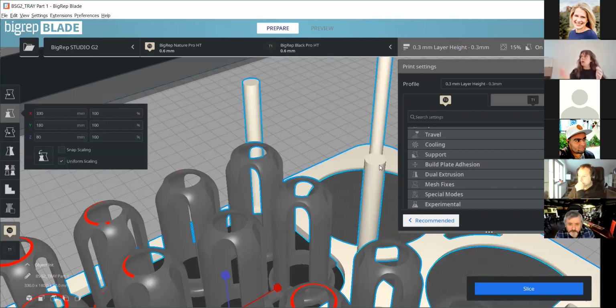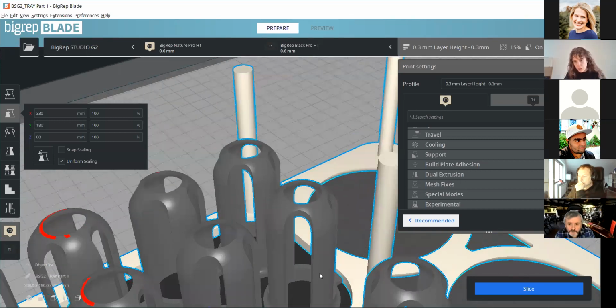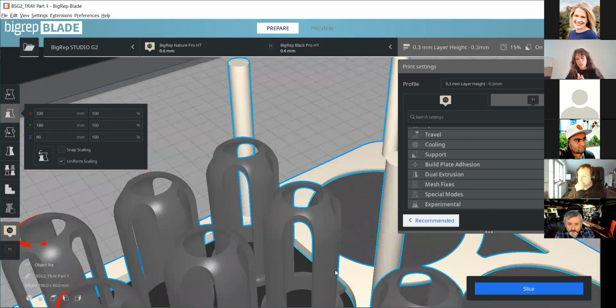But I modeled them so that the two elements, like you see this element here where they touch each other. Yeah. Those two meshes essentially are almost overlapping or right up against each other. So that when I bring it in here, when it prints, the outer layer of this element will adhere to the outer layer of this one and they'll print as one piece. Okay.